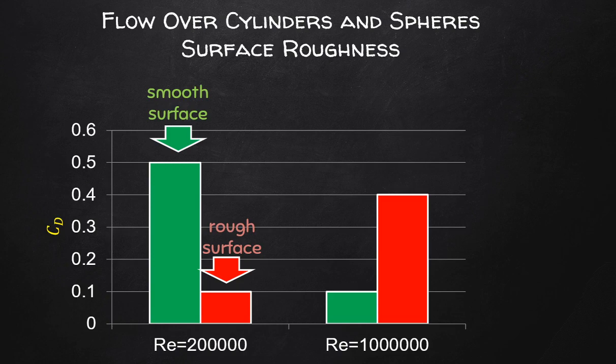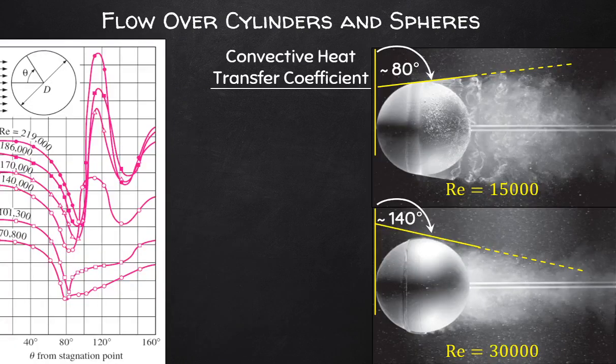friction is experienced. Now, of course, since there are different regional characteristics of flow across the surface of a sphere, there will also be differences in the Nusselt number, depending on whether you are in front or at the back of the sphere, and also likewise the convective heat transfer coefficient. So firstly, consider the change in the angle for the wake development, at what angle it starts to develop, how this would contribute, such that there are two distinct regions for the Nusselt number as it develops.